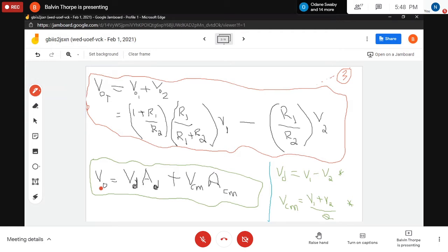So we spoke earlier in this class about things like noise voltage. If the noise voltage is present at one input, it's going to be the same noise voltage present at the other input. So we would say that the noise voltage at both inputs would be common, right? So the amplifier is operating in the differential mode, but it's also operating in the common mode as well.